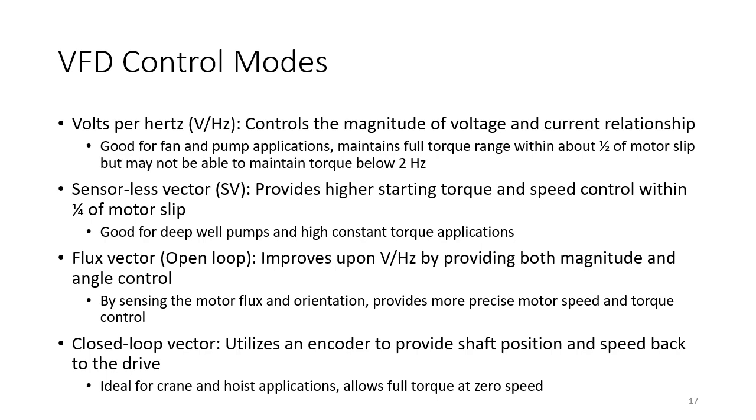For higher starting torque and better speed control, we can get sensorless vector control, very good for these deep well pumps and these high constant torque applications. But of course it costs more, so what you'll find is in a VFD, as you add more of these modes, there's extra electronics, more powerful electronics, it does increase the price.